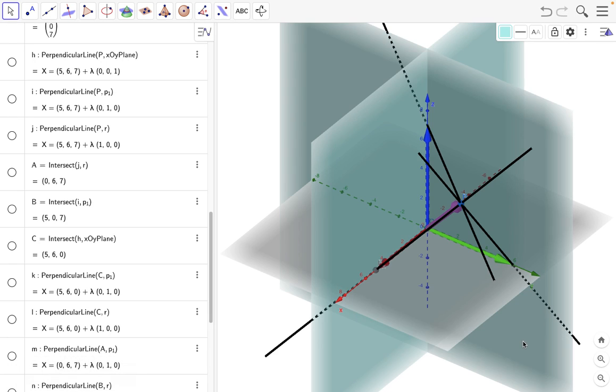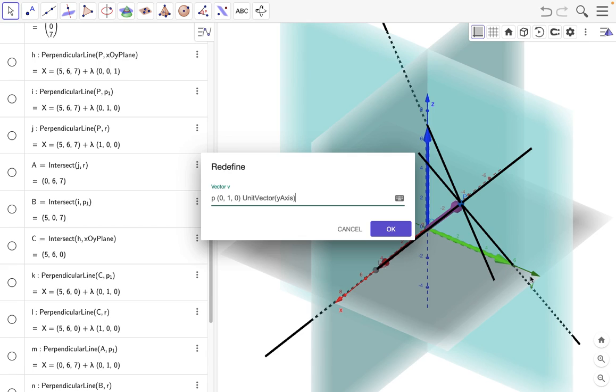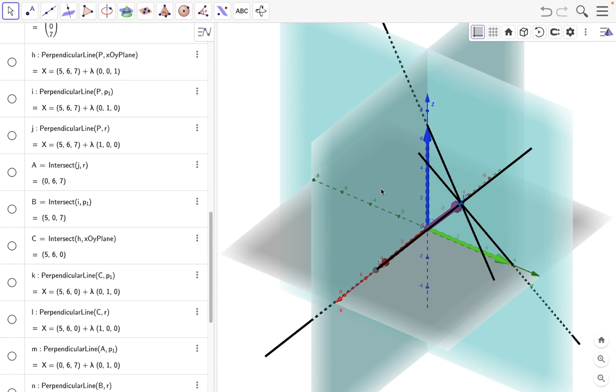Let me select that. Yes, this one. The red line is perpendicular to this plane, therefore this is called the x plane. Actually x plane means the yz plane, because y and z both are perpendicular to the x direction, therefore the yz plane is definitely perpendicular to the x direction, and that is also called the x plane in a different nomenclature. And what is the y direction? Green. Therefore what is the y plane? This plane is the y plane, perpendicular to the y direction.